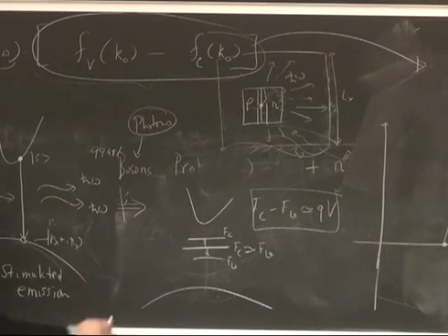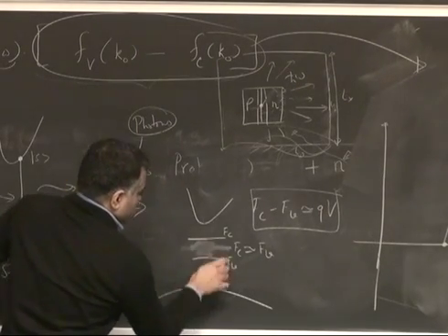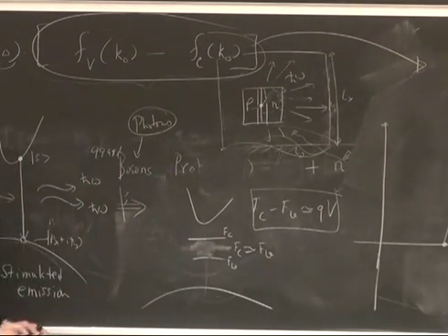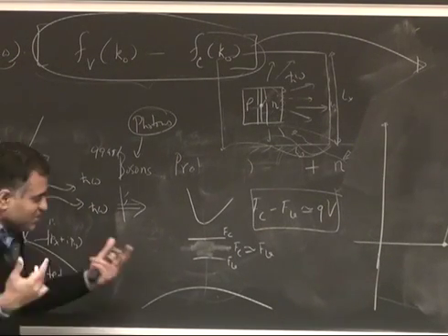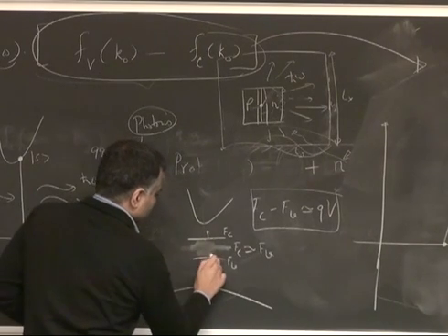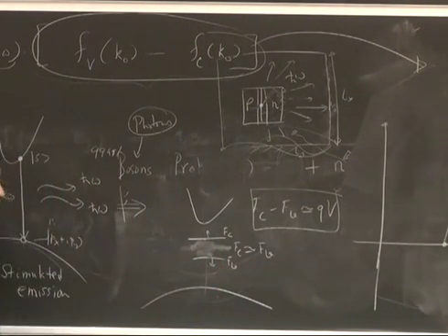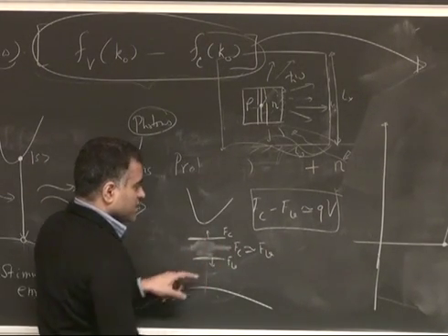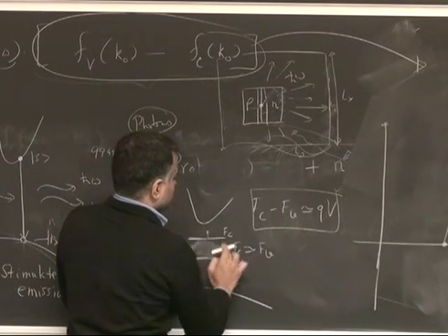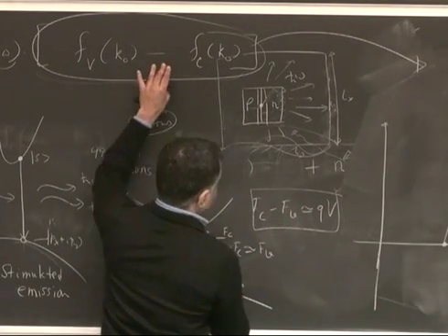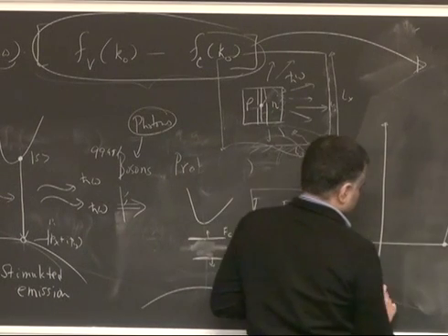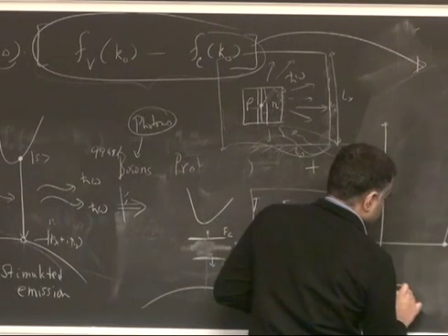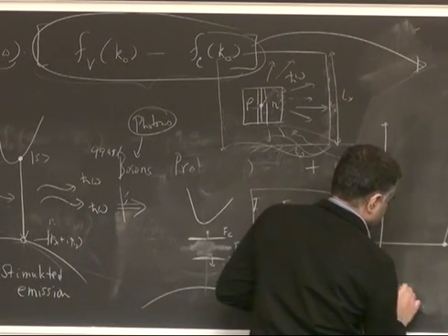Right? So as you split it, and I'm talking primarily of forward bias now, because we are going to inject carriers and make an LED or a laser, the levels start floating up and floating down. Now I can make a sketch of this condition when the Fc is here and Fv is here. You can take this Fc and value of Fv, plug it into the whole thing here, and when you plot the value, what you'll get is something like this. Let me just draw a dotted line here.